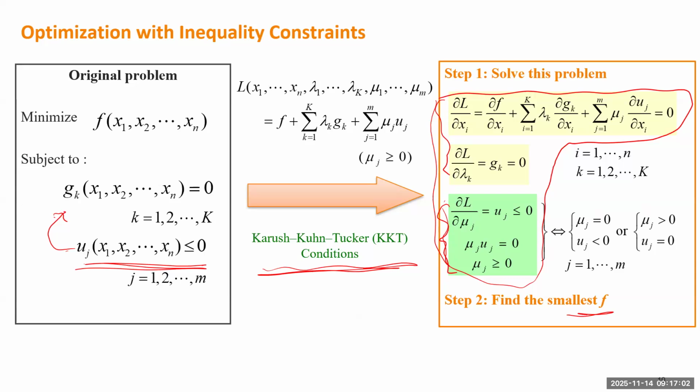If you deal with a really high dimensional problem, usually you need to program some solver to solve the yellow and green equations or inequalities. But fortunately, we are dealing with lower dimensional problems, at least in this section. We deal with economic dispatch, so we don't have so many variables. We only have as many variables as power plants, right? So we don't have to really program anything when using this KKT condition.